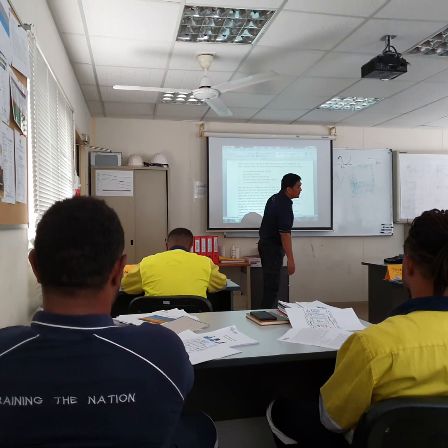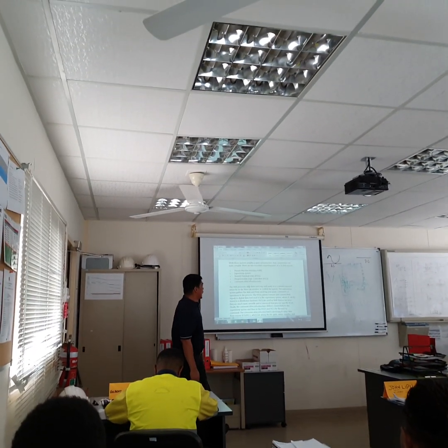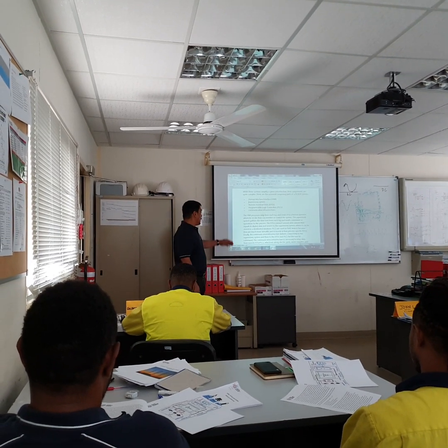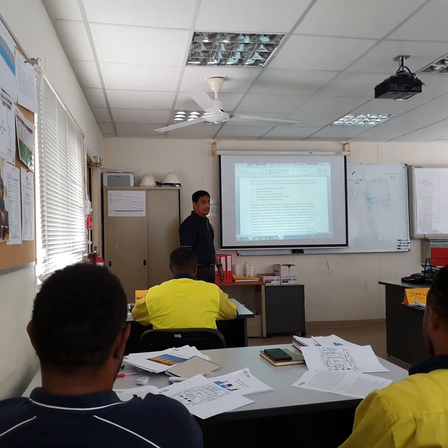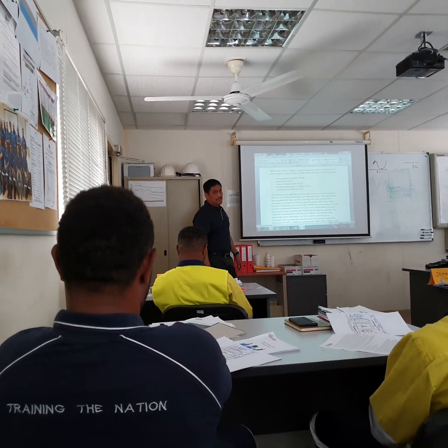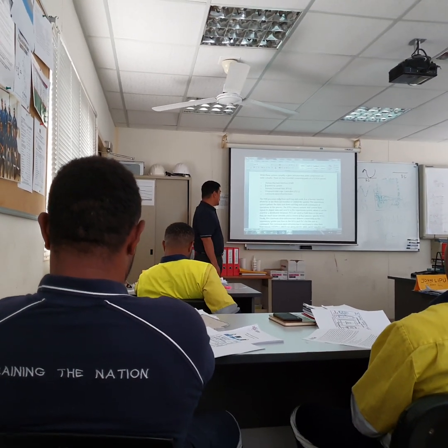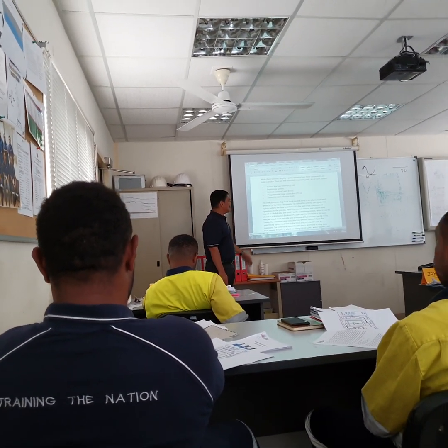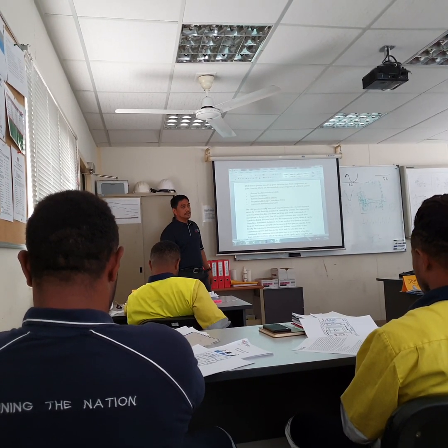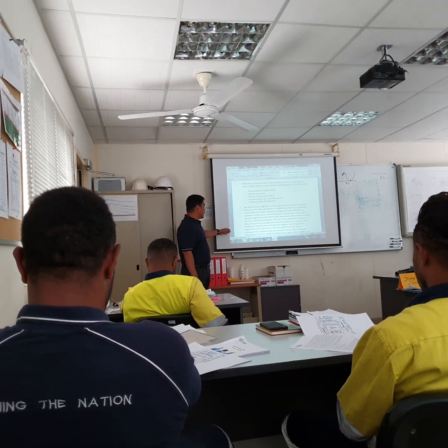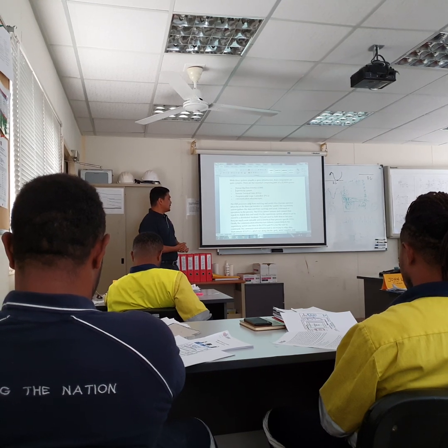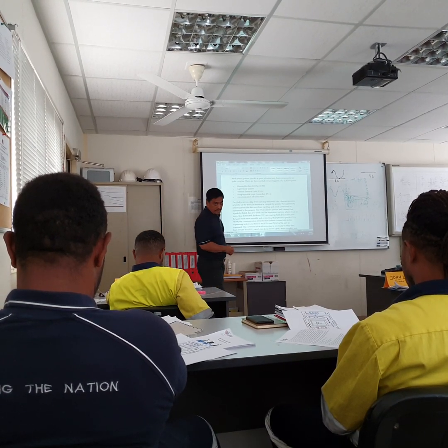So the HMI processes data from each type and sends it to a human operator. So you are the human operator and the HMI processes its data. The RTU, or remote terminal unit, connects sensors and converts their signals to digital data. PLCs are used as field devices because they are much more versatile and economical than process specific RTUs. Finally, the communication infrastructure delivers connectivity to the supervisory system and then to the RTU and PLC.